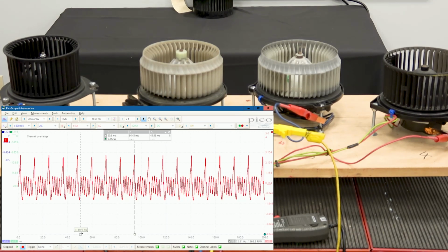Now the motor runs fine, it doesn't make any odd noises at all. I put my tachometer here, and it's running about 5,200 RPM. A typical brush type motor at high speed will run 5, 6, 7,000 RPM, so it's running at the proper speed. It's not making any noise, but there's probably a segment that's worn, right here. We get a little amperage spike on the segment right after the worn one.